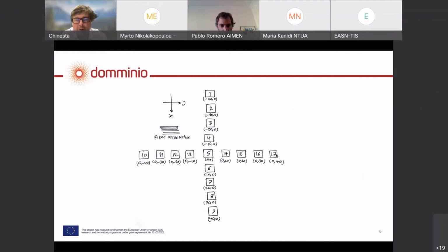And for each one of these surfaces of each one of the sheets, we are making 17 measurements in different locations to have repeatability, and in order to isolate the profiles along the fiber direction, in the perpendicular direction to the fibers, and probably in other orientations.